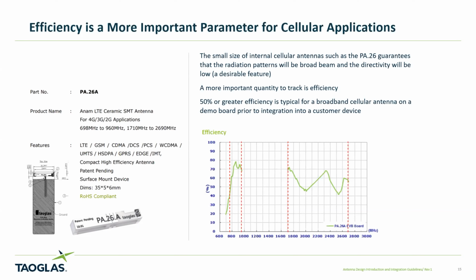Not that I've seen, and the main problem with dielectric loading of an antenna or even a ground plane or other regions around the antenna is you need to make sure the dielectric has a very low loss tangent, a low loss material, and then it tends to reduce the bandwidth. So as you go from a well-sized antenna to a smaller ceramic-based antenna, typically you see the bandwidth shrink. The efficiency tends to stay high, but it really forces you to ceramic materials with very low loss tangents.